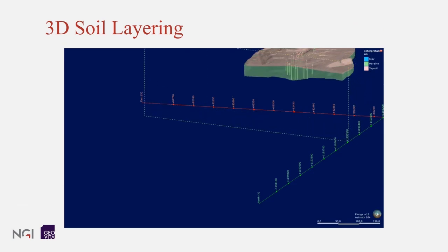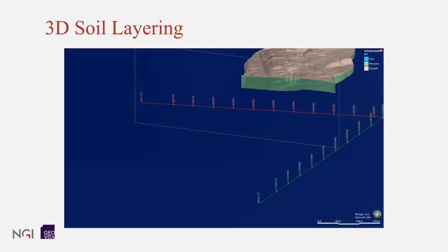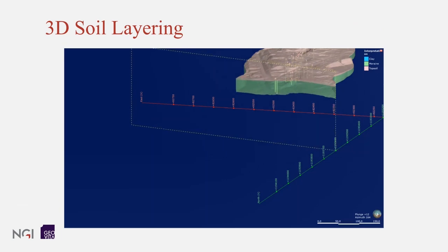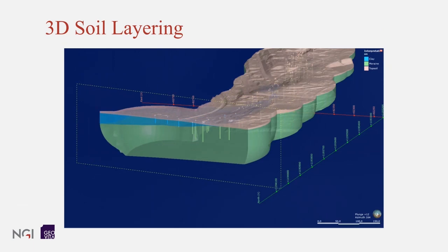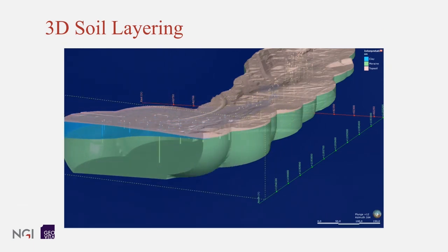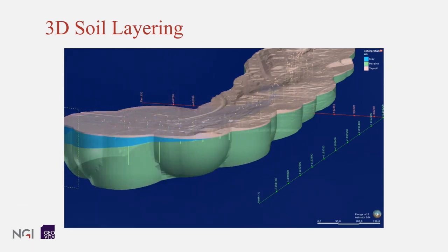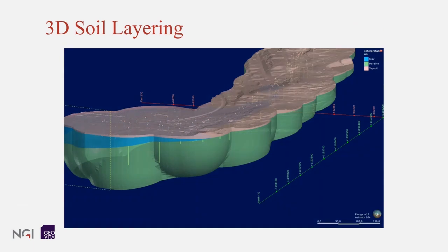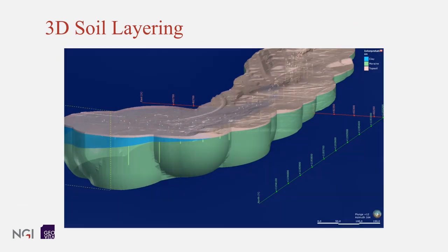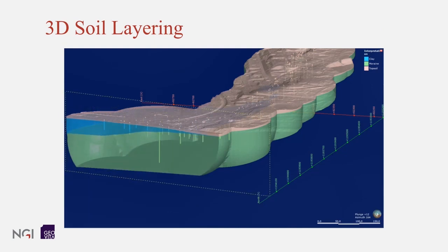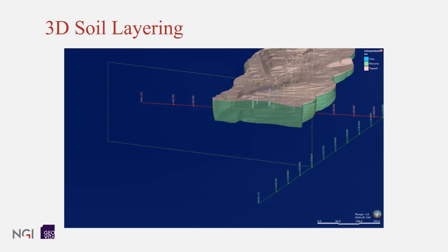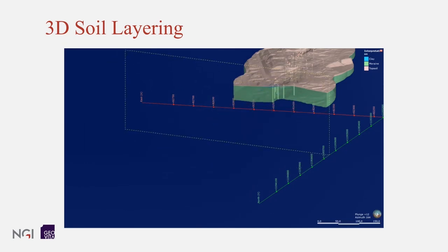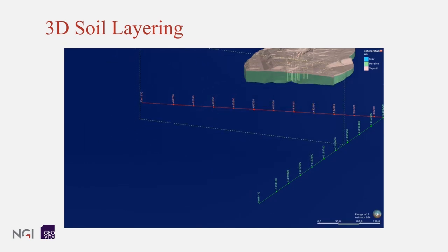The strength of this method and software is the visualization. It is easy to spot errors in the dataset or with your interpretation. And you can play around with how you interpolate or set up your model until you're happy with the result. Another great thing is how easy it is to add another borehole or more boreholes. You just put the coordinates into the spreadsheets, upload them, and then the whole model updates within a few minutes.